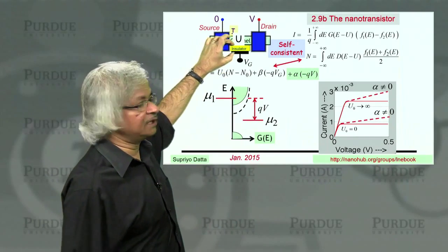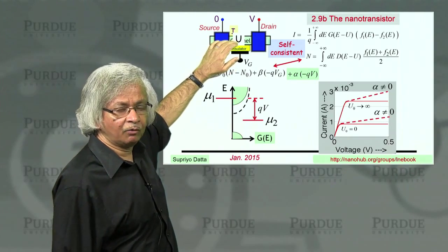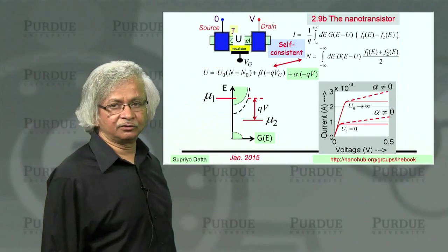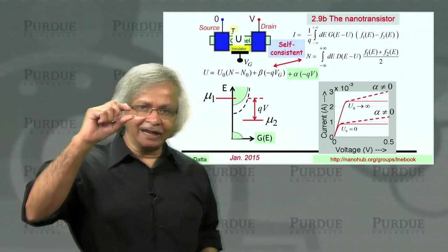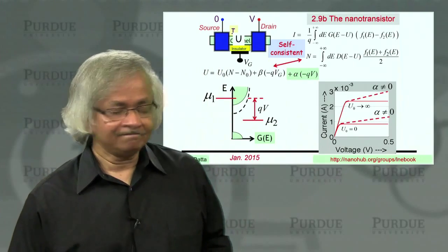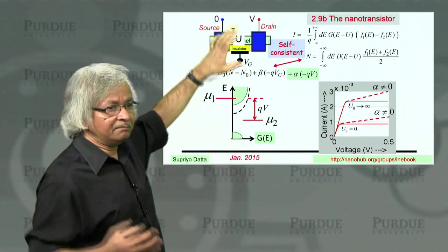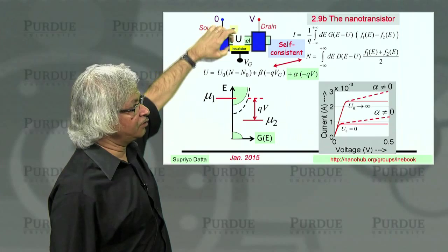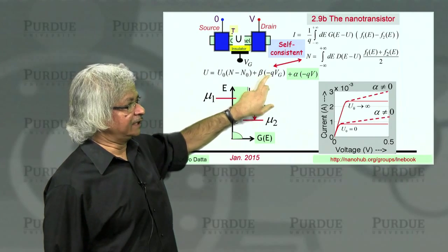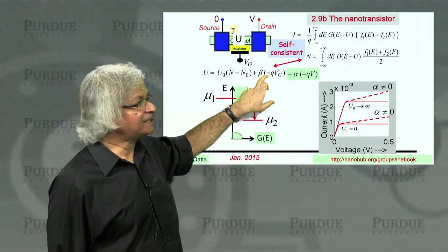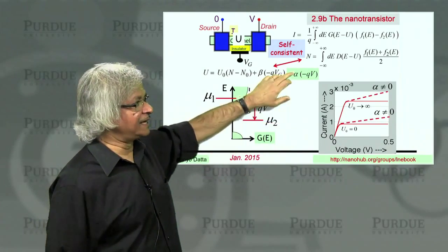And that, of course, is extremely hard, because once it's thin, it also means there will be leakage currents, more and more leakage currents as electrons tunnel through that insulator. Not to mention that it's very hard to control something to 10 atoms across billions of devices. So that really is the major engineering challenge, in terms of how to make billions of these nanotransistors work: how you can make the insulator thin enough that the gate controls the channel potential much better than the drain controls it. So that's kind of what determines a well-designed transistor.